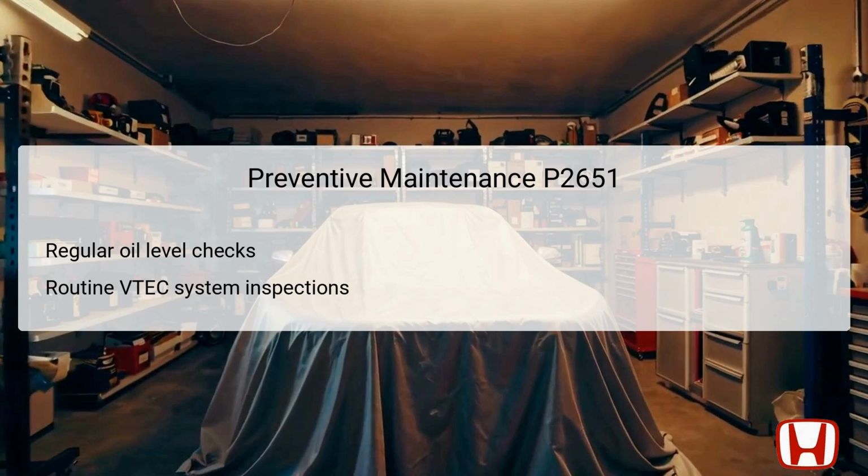Preventive maintenance is a vital aspect of ensuring long-term reliability for vehicles, especially regarding the VTEC system in the Honda Civic. One of the primary maintenance tasks is to regularly check the engine oil level, ensuring it remains within the manufacturer's specified range. Adequate oil levels are essential for the proper function of the rocker arm oil pressure switch and the overall health of the engine. Scheduling routine inspections of the VTEC system can help in identifying any potential issues before they escalate into serious faults, such as DTC P2651.